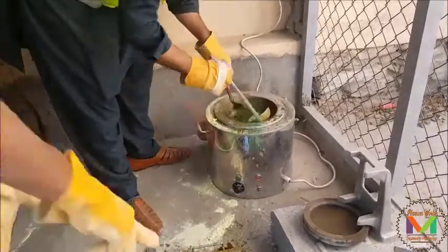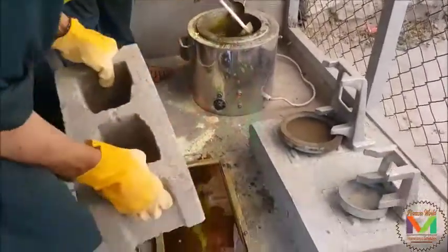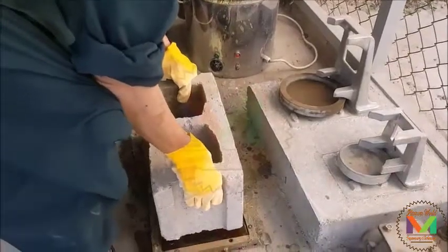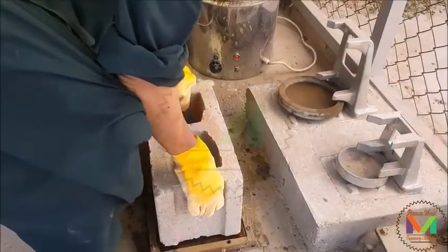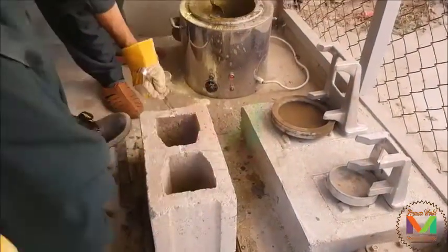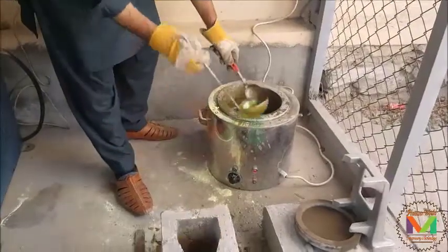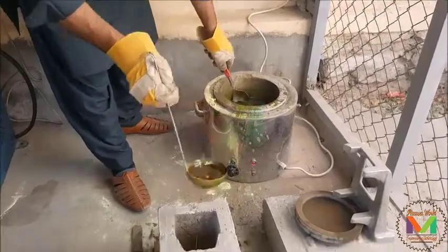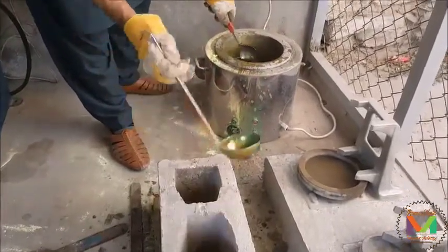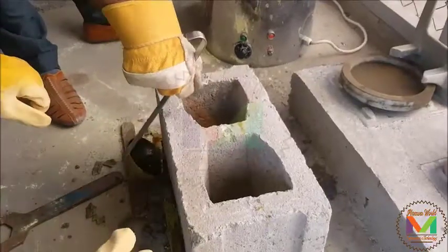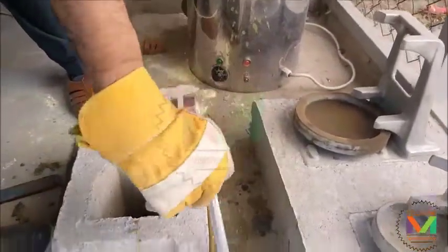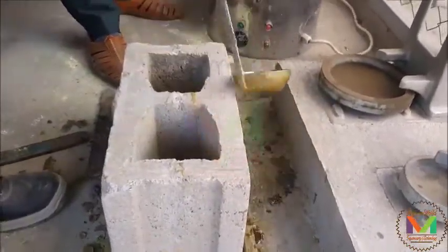Place the sample into the capping mold, as you can see now. Our capping mold is on a very flat surface, which is rigid as well. I have checked all sides of the specimen, and there is no gap left.